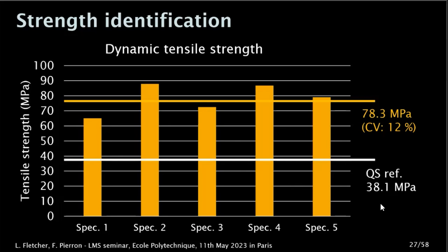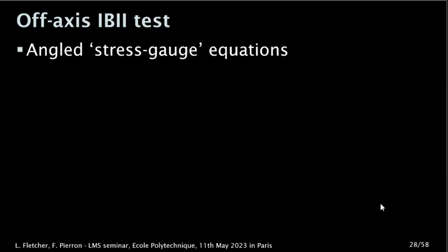And here you see a very large increase from the quasi-static, because failure is much more sensitive, of course, to strain rate, because you're not activating certain dissipation mechanisms in the material when you load much faster. So that's not so surprising.